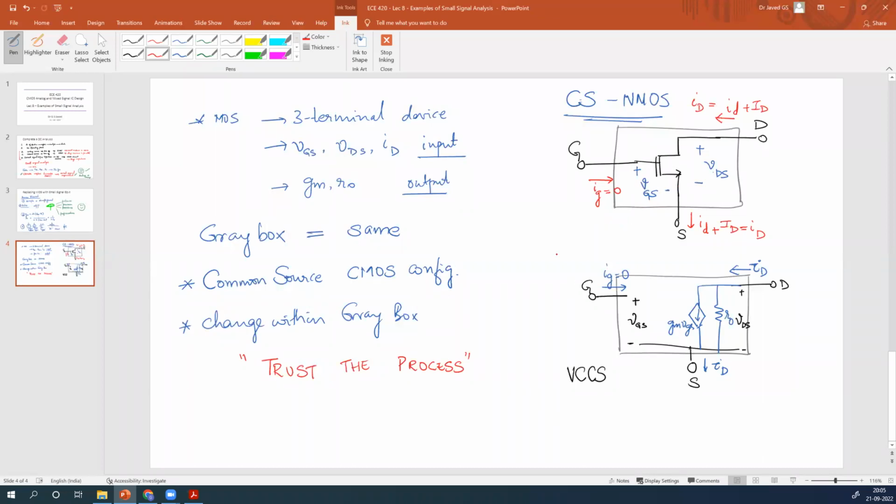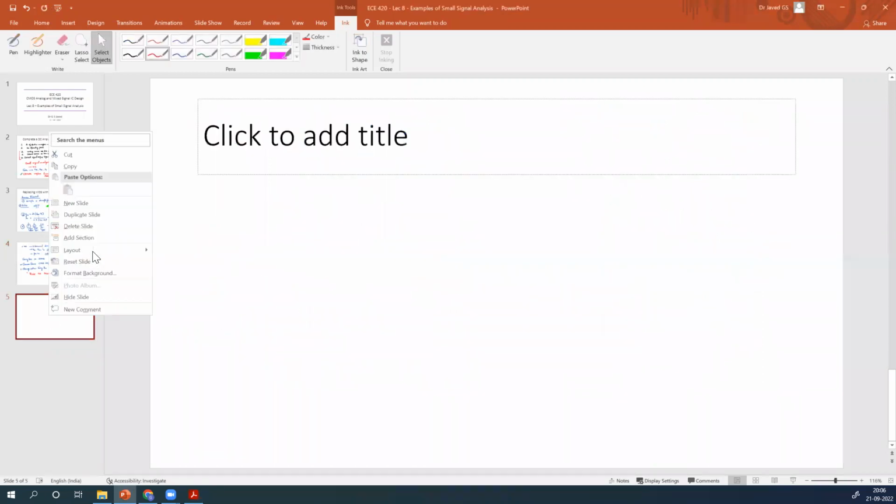Sometimes you do not need to add anything, because in your small signal analysis it is not needed. Large signal will not be needed. Voltage sources and current sources are all large signal, so you can bring them out, either ground it or short it, or connect it to VDD, to the nearest AC ground. That is the process that you will follow.